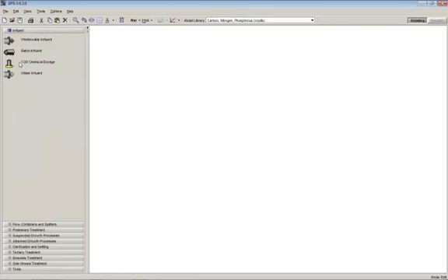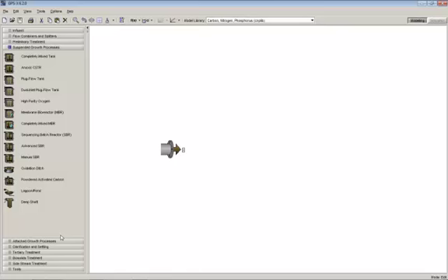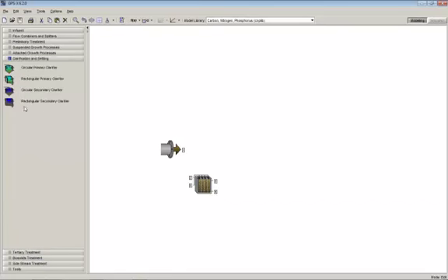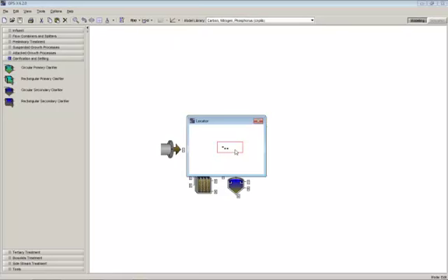So what I'm going to do is start out by building a very simple model. You don't always model the whole plant for every project. I'm going to build just the activated sludge portion of the plant for this demonstration. So this is an influent object that is going to describe the flow that's coming into the plant. This is an activated sludge unit, a plug flow tank, as I mentioned before, and then we're going to use a circular secondary clarifier. So I'm going to zoom in here a little bit.